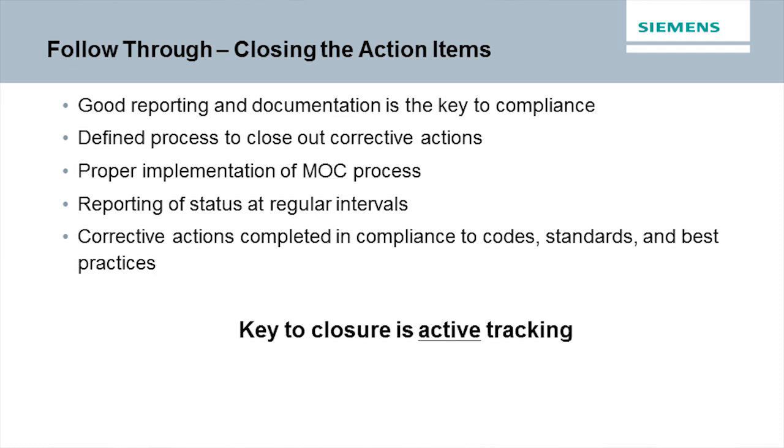If we say we're going to replace this vessel at the next outage, there had better be ongoing motion to get that activity into your project team, your engineering team. There's a project assigned, there's budget being approved, there's a scope being developed, and so on. It's not just, it's in the work order system that we got these findings, we wrote a work order, and we told maintenance to fix it, or whoever's going to fix it, or things like that. Well, there has to be a follow-through, completion date, status tracked or reported on a regular basis, because these are the things that actually cause failure, loss of containment, and catastrophic incidents.